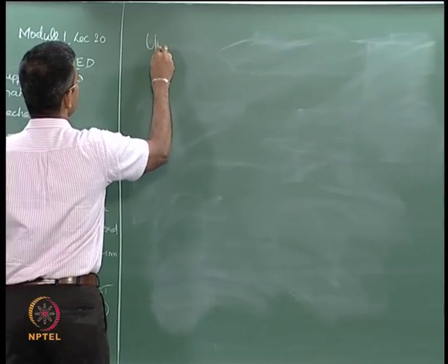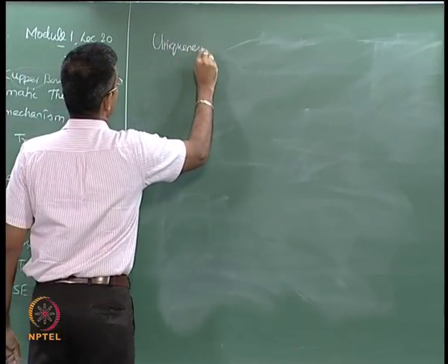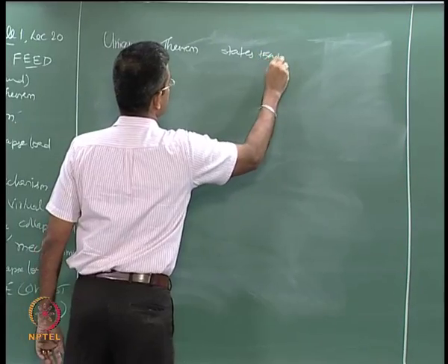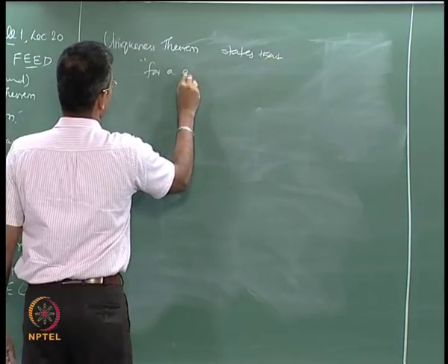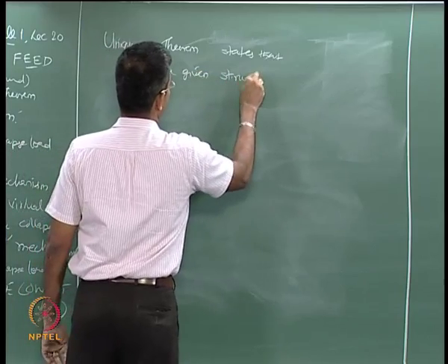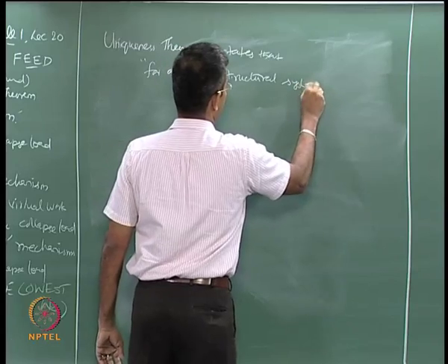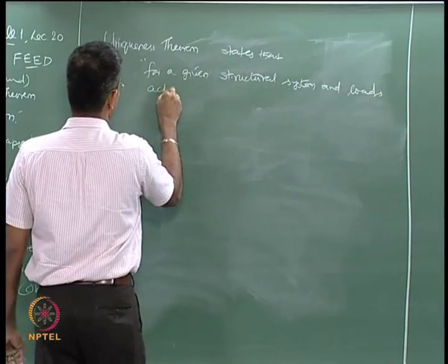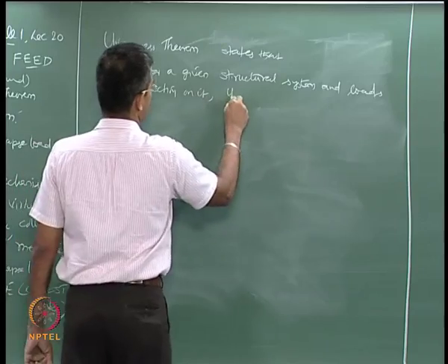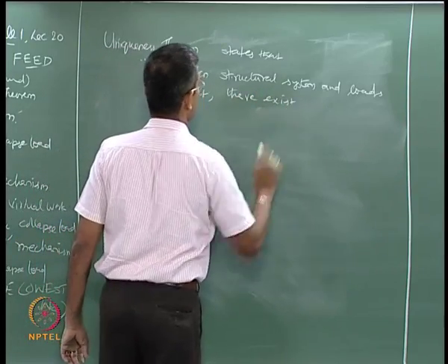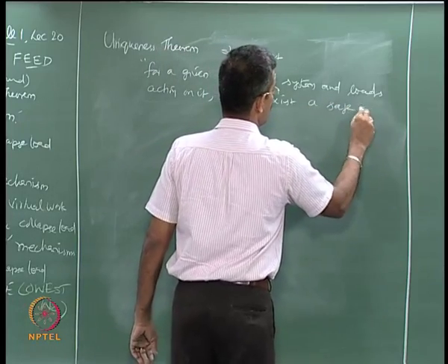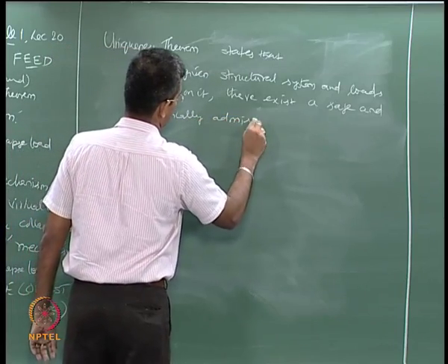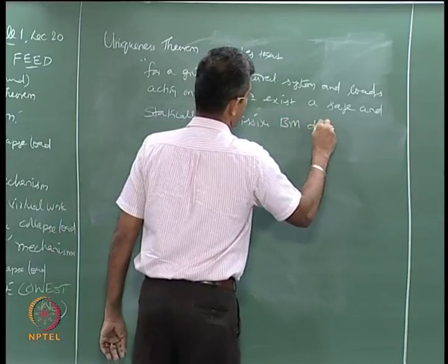Uniqueness theorem states that for a given structural system and loads acting on it, there exists a safe and statically admissible bending moment distribution,